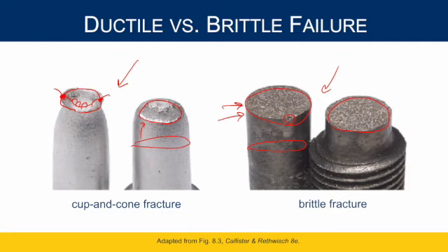But the main reason too is the shape of the void actually amplifies the stress. So say I have 100 megapascals of stress in this piston. The piston's supposed to handle 150 with no problems. The edges of this void, because of its shape, actually amplify that stress, and it could be seen 200, 300, 400 megapascals right at the edges, which is well above the 150 that the piston was spec'd for. So it starts to crack and propagate, and all of a sudden it goes through the material and it fails in all directions.